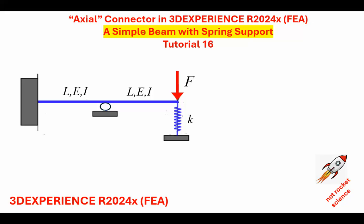Now, in this problem that you see there, it's a very simple 2D frame problem or beam problem, where the left end is clamped, the middle point is on a roller, and the right point is subjected to load. There's actually a spring sitting there. Now, I want to model that spring as a connector. The alternative is to model it with a spring element, but since currently I'm looking at the connector functionalities in 3D Experience, I will be using connector.